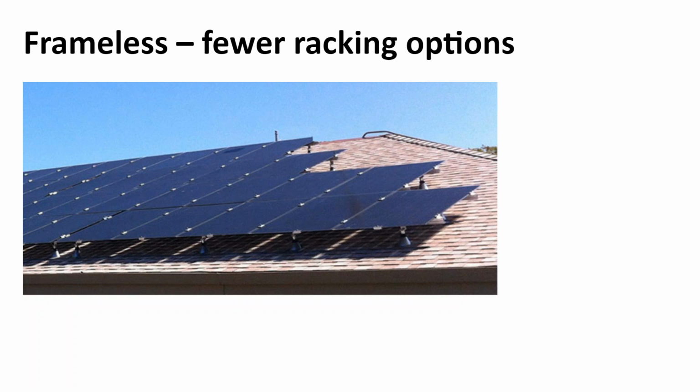I would do frameless for visual aesthetics, and I don't think this is necessarily the best application for it. In fact, I find frameless panels to be problematic, and the reason is they have a sheet of glass on top and also a sheet of glass underneath, and that makes them much easier to break. And so all glass panels, I wouldn't use them in this manner.